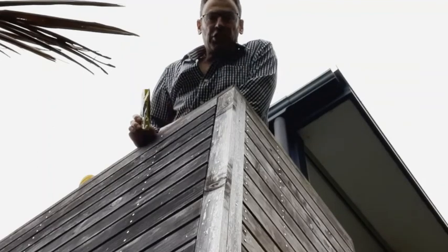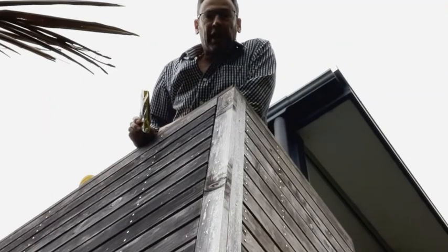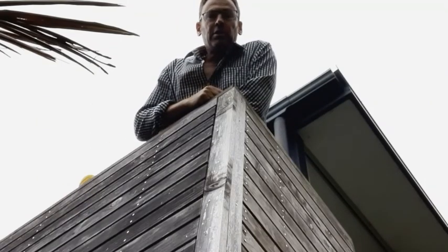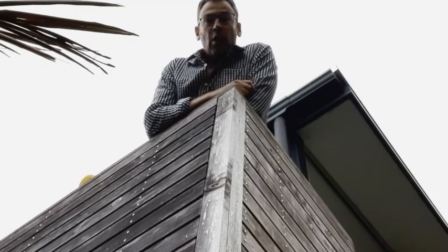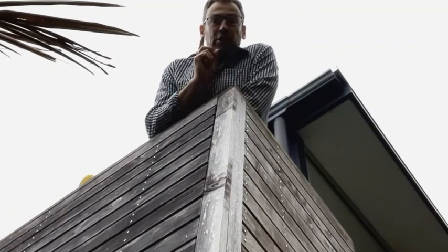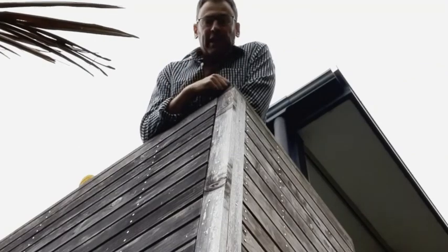Now, from the ancient Egyptians to the infrastructure of today, gravity is what has been used to measure height. More specifically, what we need is an equal potential gravitational surface to reference as a height datum. That's quite a mouthful, but the most common one we use is mean sea level.